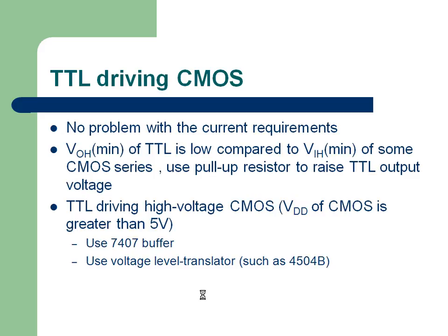Output is high means this is off. When this is off, there is no current path. Here, there is only a current path between these two, like let's say this is RC1, this is RC2. Now effectively what happens is, if this is 3.0 and this is 5 volts, you will see 5 volts here. So by adding this pull-up resistor, you are able to give 5 volts. And not only that, you may wonder, what if they just want to give 5 volts? The intention is, by adding this additional resistor, you are able to do more. Now what will be the major challenge?